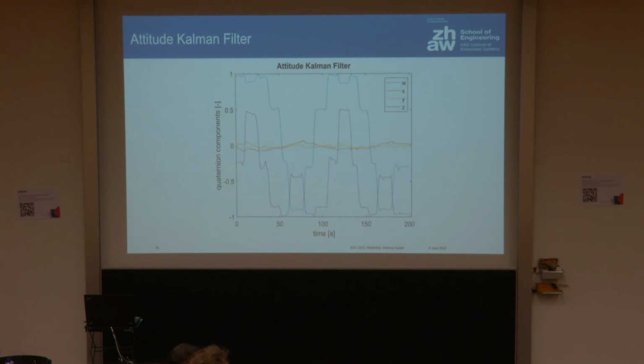So let's look at the attitude first. I mentioned that I'm representing this using this fancy and actually very, very convenient mathematical construct of a quaternion. This is slightly unintuitive, which is why I will not explain each component, but we will see that in this test drive that we did here, we were only turning around the z-axis, which is the one that is pointing through the car from the top.